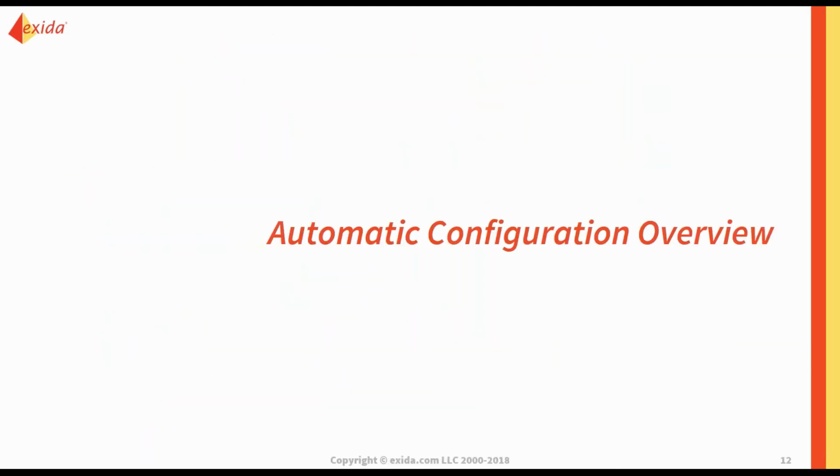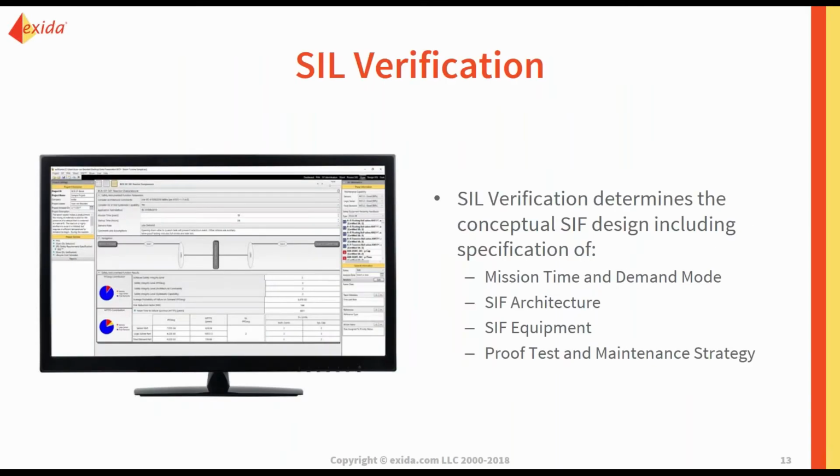So let's take a deep dive into this concept, and then I have a test case I can talk about where we use the DeltaV SIS Configurator on a project. So as I said, you're going to start with your SIL verification. Here I have a screenshot of our Silver tool in exSILentia. And this is where your conceptual design is done.